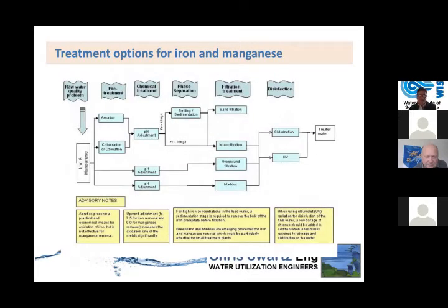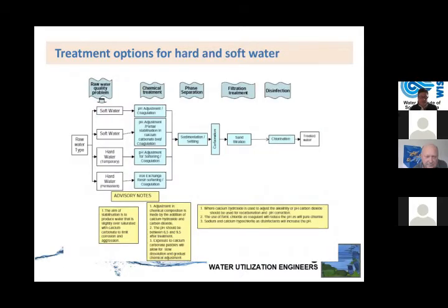Then iron and manganese in groundwater specifically, as I mentioned earlier, is a big problem. We get that all around across the country in certain areas. It can cause a lot of aesthetical problems in distribution networks and at consumers. And at high concentration, obviously the metals also pose a health risk. So the most common approach would be first to oxidize your iron, get it out of solution, and then filter out the precipitate that's formed after you've oxidized it. But we're getting to that just now.